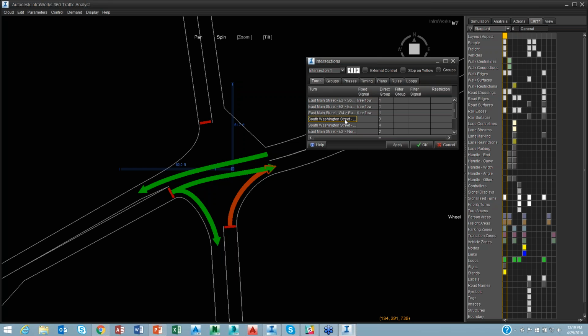However, you saw when we modeled it, we had no vehicles doing that. With the orange arrow here, that is going to be a stop sign. The orange arrow, this will also be a stop sign. This will be free flow. All right, once again, it's getting all of these movements based off of what we set our arrows to. So I'm going to set this as a stop sign from the other direction. This was also a stop sign. They had to wait. Going straight through, that was a stop sign. And then the last one was a stop sign as well.